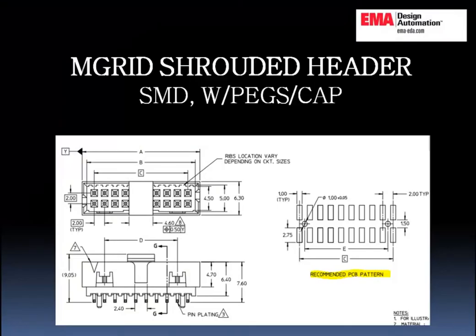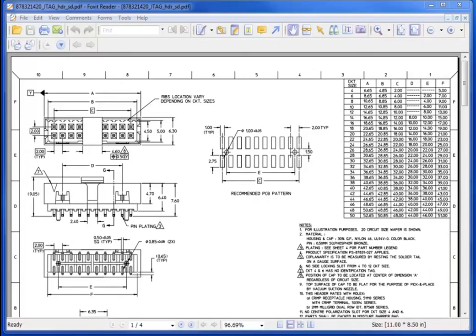In this training video, we demonstrated using the standard surface mount calculator for the ZIF device and a recommended PCB land pattern provided by the manufacturer. We also use the pad stack calculator to automate the through-hole pad stack or mounting locations, which were variances to the standard calculator, and the ability to regenerate using these variances with the reentrant calculator.